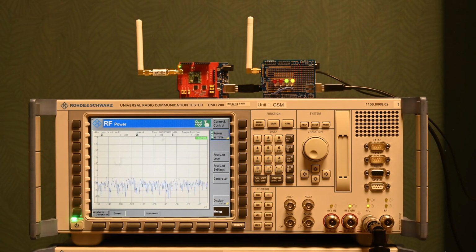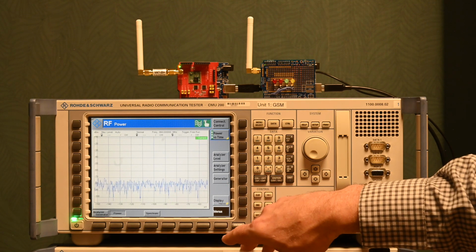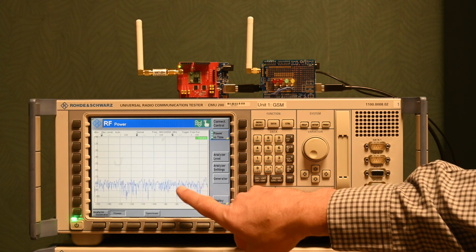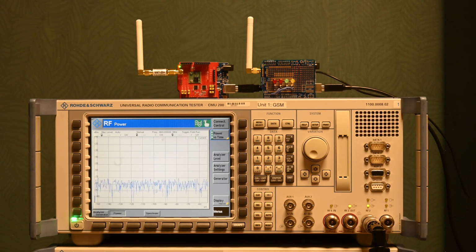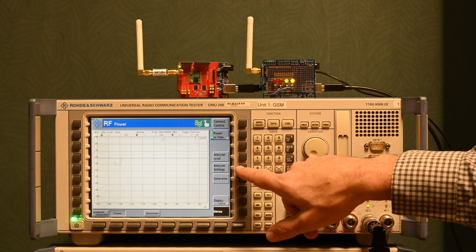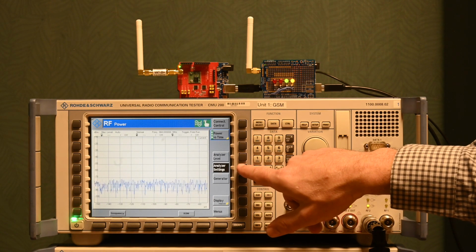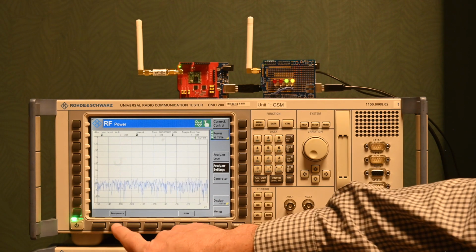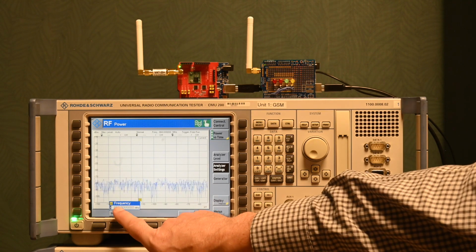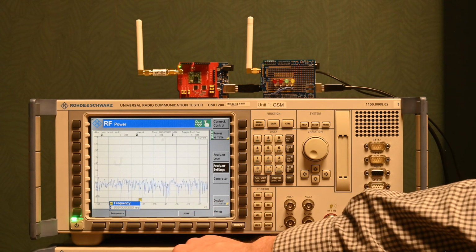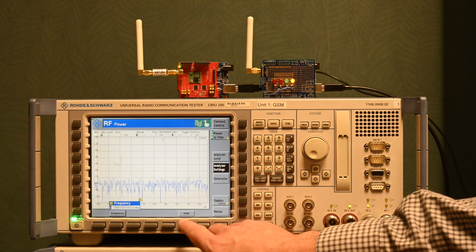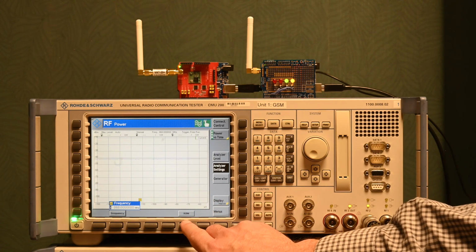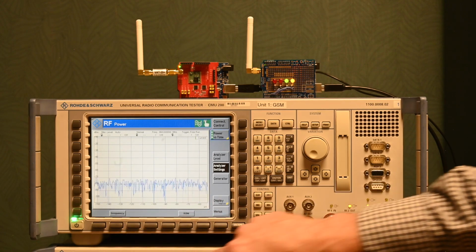And how do we do that? Well, actually by first trying to trigger this signal on the burst in question. And how do we do that? We go to analyzer settings. I should have mentioned before that I've already set this analyzer in advance on the right frequency. You need to specify a frequency, otherwise it won't work. And also a resolution bandwidth that I've already set in advance.